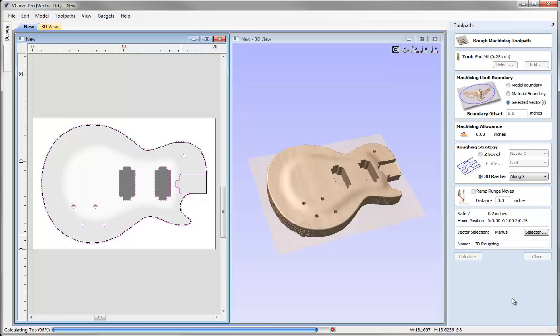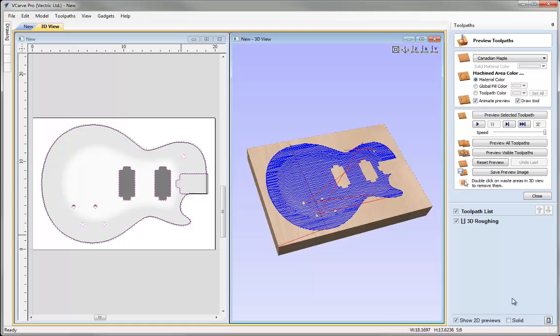And what you're going to see is the software will create a toolpath for us within those areas, so you can see it's not machining outside of those vectors, and it's just tracing back and forward over the part with quite large step over in this raster pattern, which will give me a nice clean finish on a shallow model like this, ready for me to go ahead and do the roughing. On a deeper model, or a model with a lot of Z variation within the roughing area, then you might choose that Z-level roughing option instead.